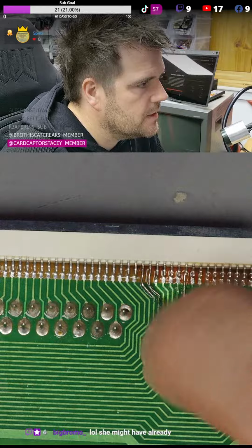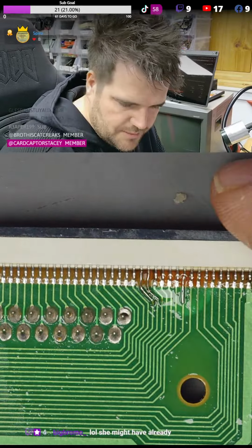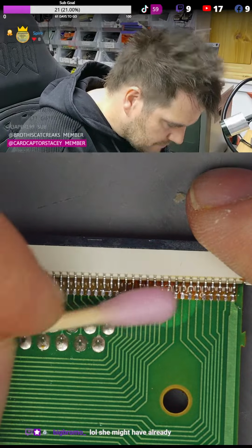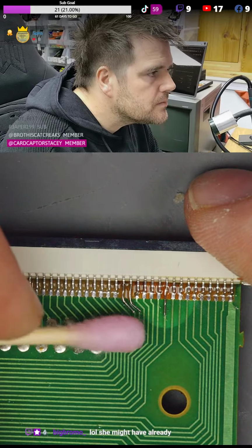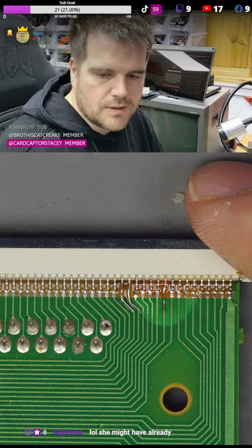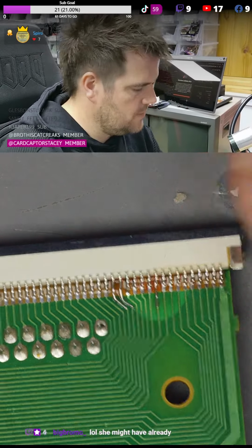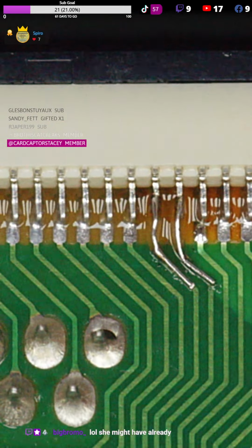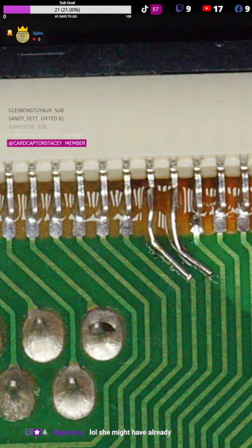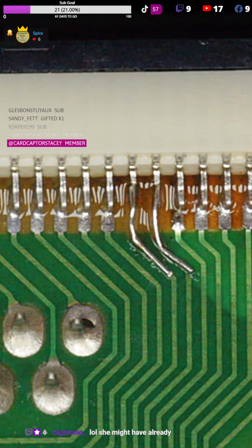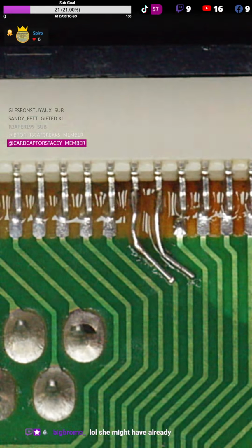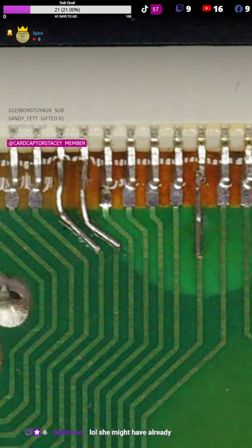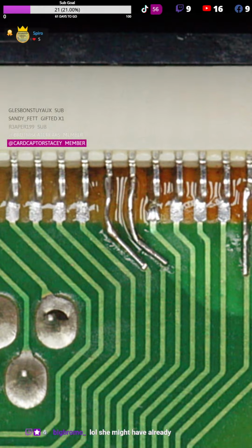So that probably needs a bit of heat on that to clear that up, but that's basically how you repair them traces. Is that all the way zoomed in? Yes, it is. So let's use the extra zoom, but that's a nice repair. Now you could cover these in conformal coating or the resin or something, but I'm not going to. This is such a simple repair, and nobody should be going in here with hot air or rework anyway, so I'm just going to leave them exposed basically.